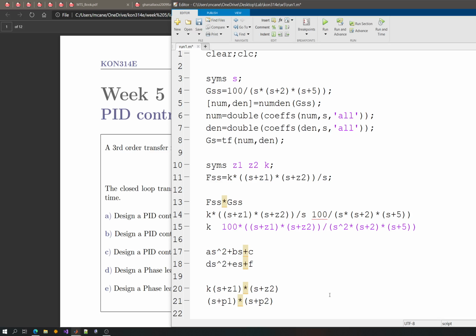It sounds easy to choose these zeros and poles, but the actual problem lies in choosing these parameters here. And therefore, we have some approaches. One of them is a pole zero cancellation method. Of course, you're not trying to cancel your zero Z1 and pole P1 in the controller, because if you do that, you will end up with a different controller.